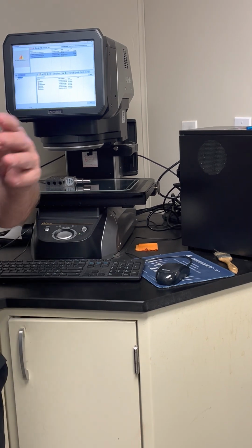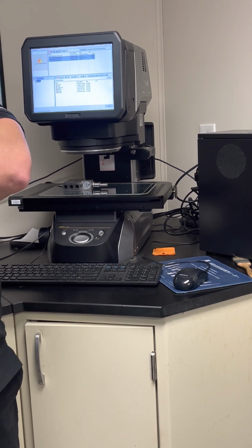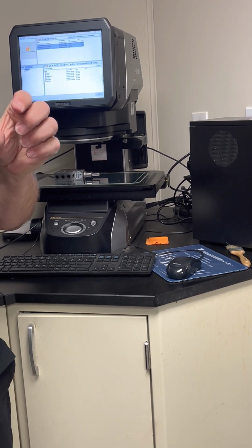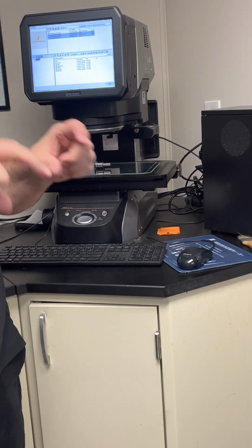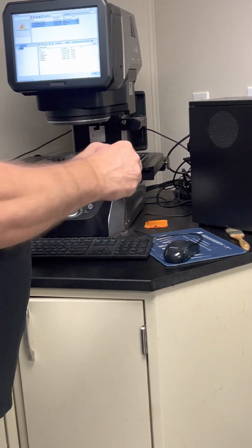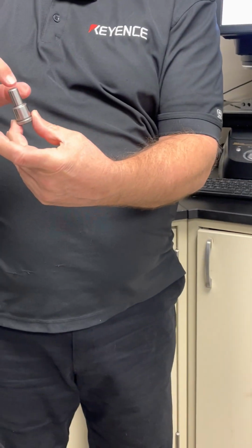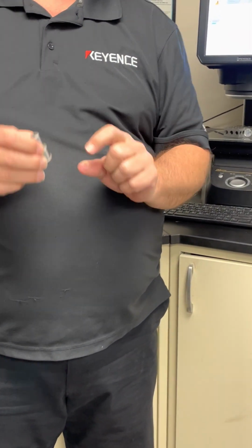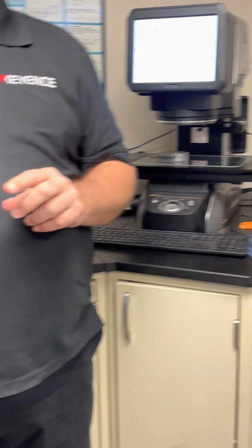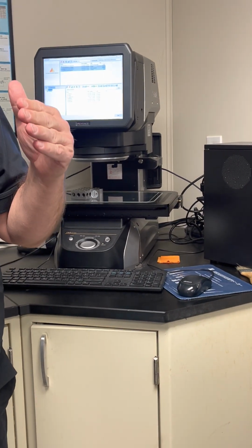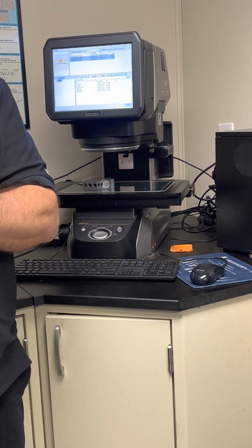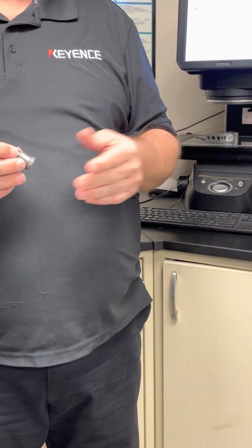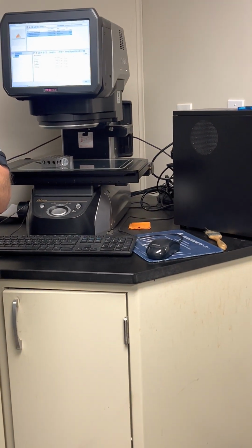And again, I think the key thing is when you go to measure the part, just take a look at the part and any turned part like that. Everything on the ends is going to be one focus. The top and the bottom is going to be another focus, and those little ones in there are going to be another focus as well. So realistically, on something like this, I'm going to have pretty much just two focuses. Again, you just want to avoid focusing it here, then focusing it there, then refocusing it. There's no reason to do all of that. This would just make it a lot easier.